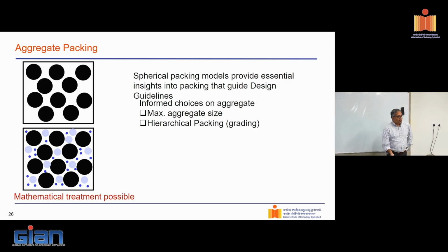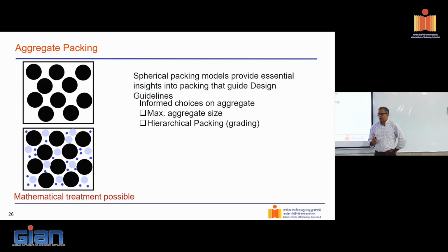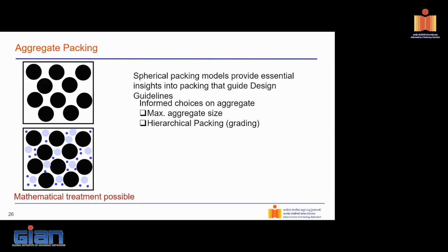If I overdo it, not going to help either, right? Then maximum aggregate size plays a role. How? If I start with a larger initial size, I hope to hit a larger volume of solids, which means I improve my packing density. And that knowledge I gain from playing with spheres is going to be smaller.